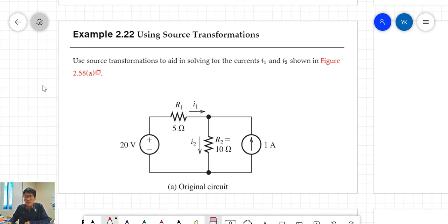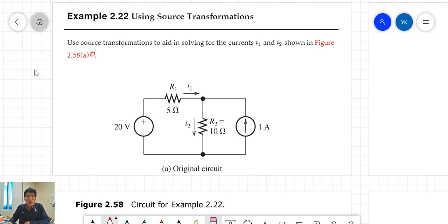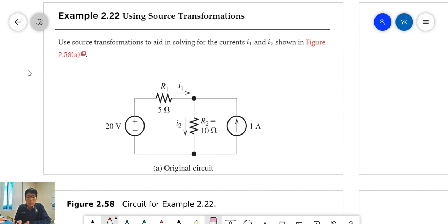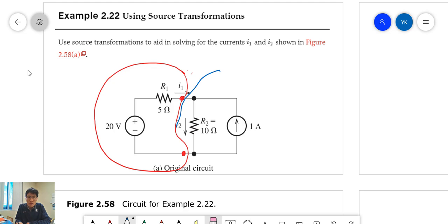One other example here. Now the circuit was given with one voltage source and the other one a current source. Look at this. If we disconnect it at 2 points, then this circuit seems like a Thevenin equivalent circuit, and the other part from here to here is a Norton circuit, and the other one is a Thevenin circuit.